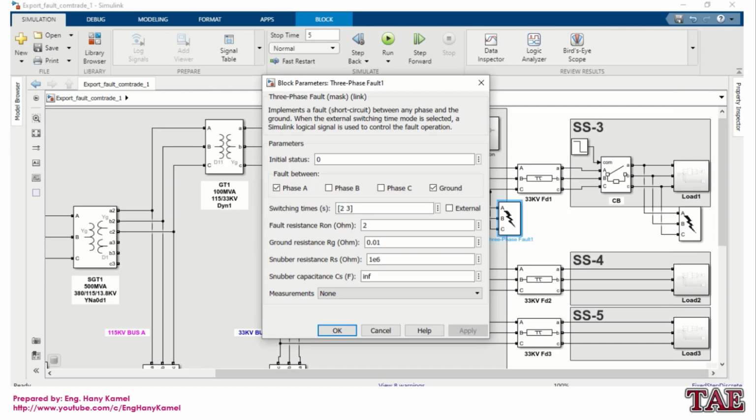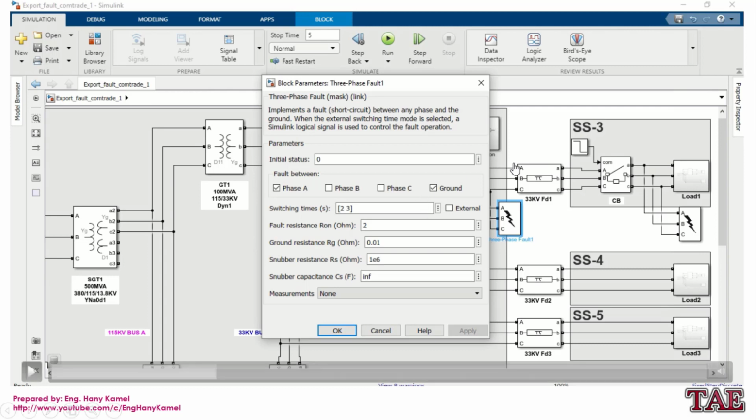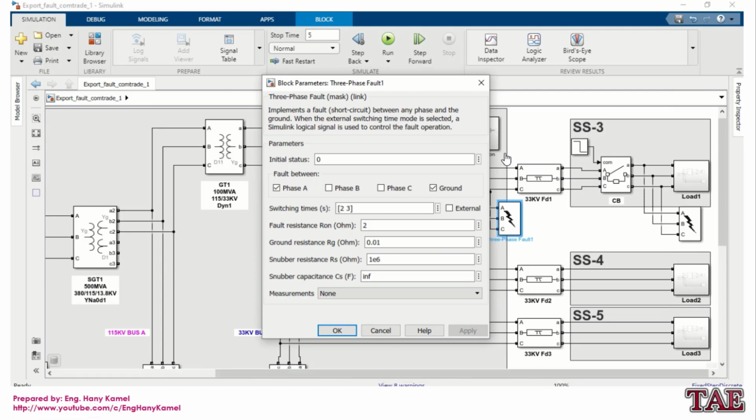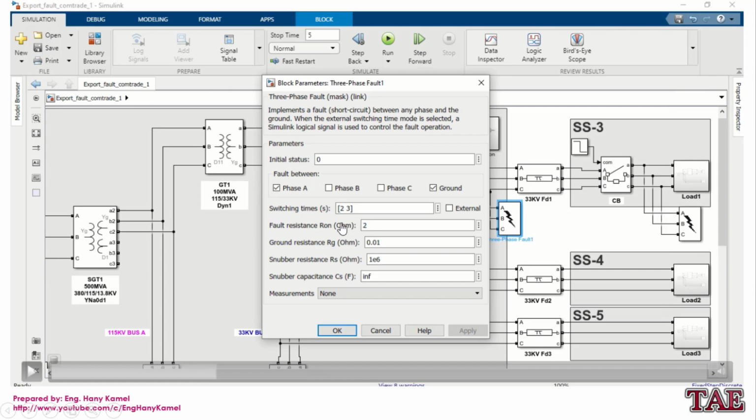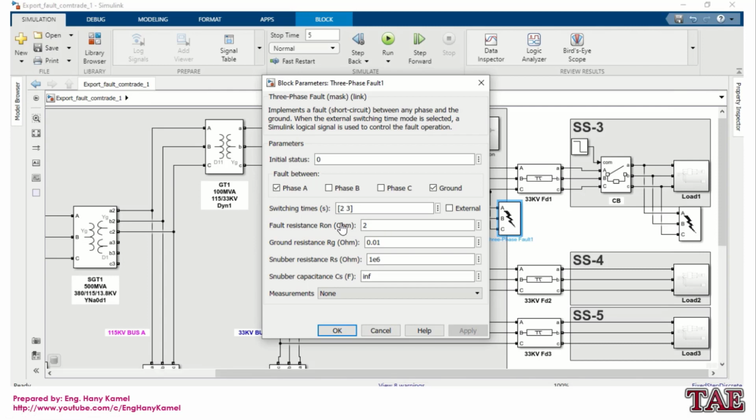Then, due to the first fault, some stress happened on our system, so the fault will be regenerated or reinitiated, but in our substation 2, with a higher stress fault, meaning it will last for 1 second. Actually I disabled the trip circuits, so it will not trip the circuit breaker, because I need to record the fault for more time.